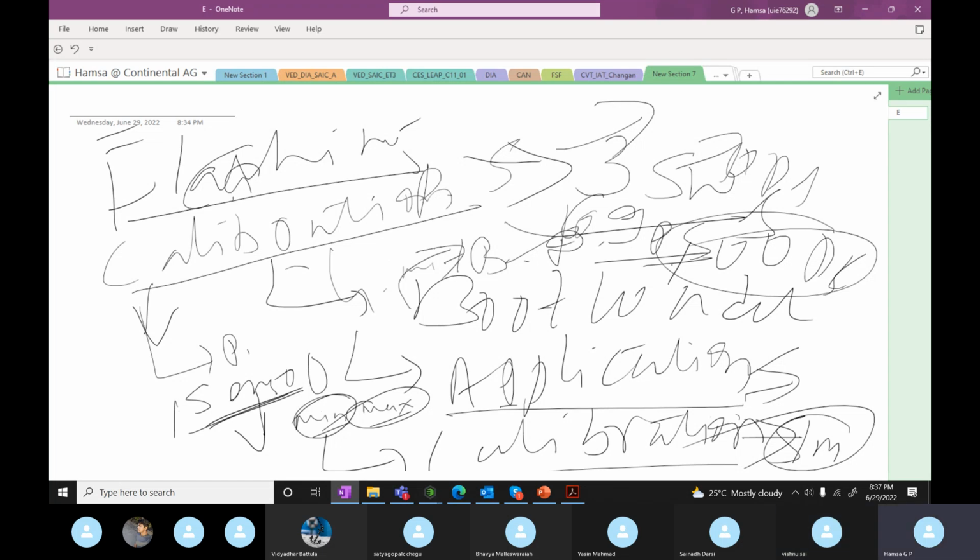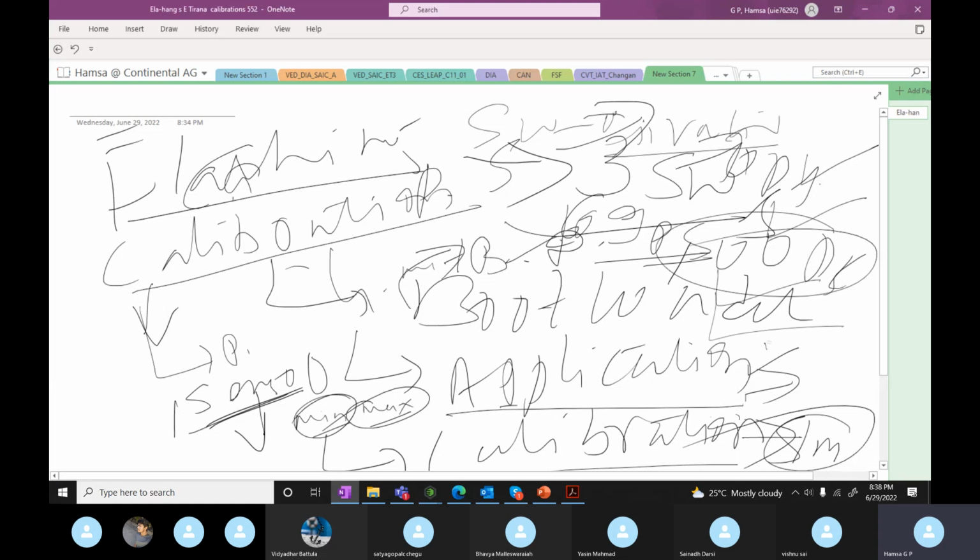So how does the software know that a value is invalid? It is invalid with these limits, correct? All those values have a minimum value and a maximum value. For calibration also there will be a fixed memory, like 128 KB. Inside that 128 KB the memory is completely fixed for the calibration, and from the starting address to the ending address, each and every byte says something.